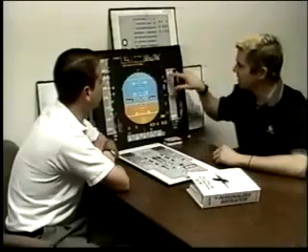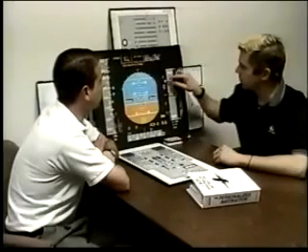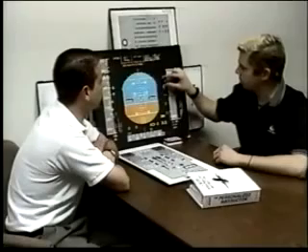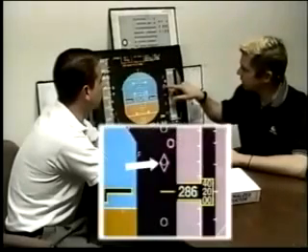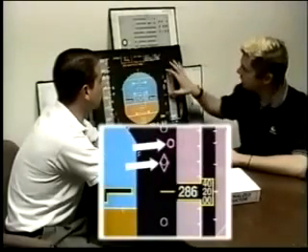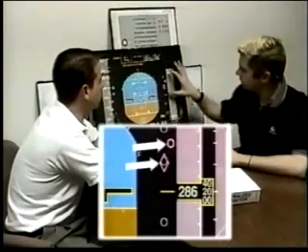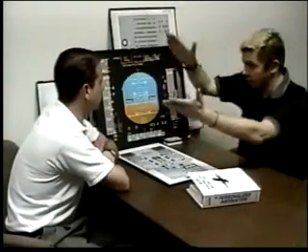This is also similar to the VDEV, whereas if we're on the approach nav approach, it's still a VNAV deviation, but it's a shoebox, and it is now 200 feet instead of 500. Big difference here between the ILS and the vertical navigation stuff. This is a very linear type of display. It's always 500 or 200 feet all the way down, whereas if you've got the glide slope, it's angular. In other words, as you get closer, the constraints get tighter and it becomes more sensitive.